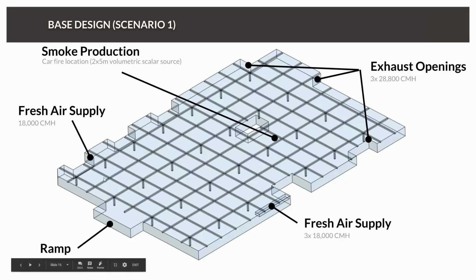And at some points, first of all, we are bringing fresh air into our parking garage. And this is not only necessary in the case of fire, it's also necessary in day-to-day operation, but for sure, usually when you have fire, you use a different ventilation strategy and different flow rates than in day-to-day use.